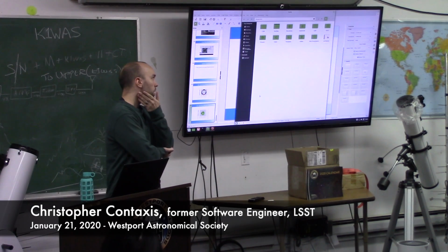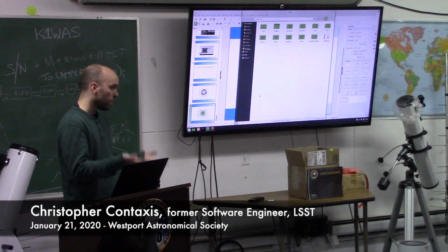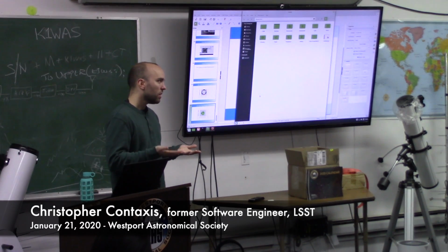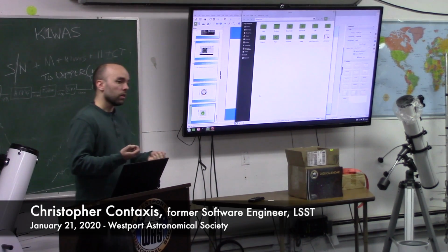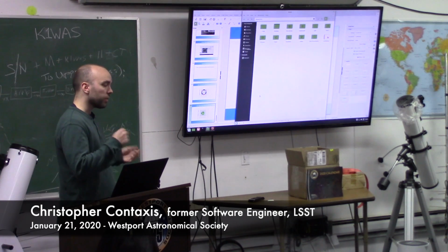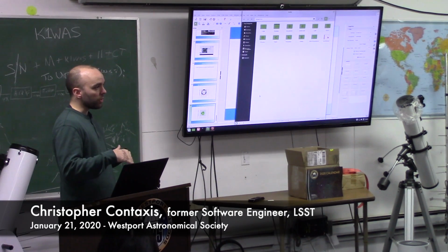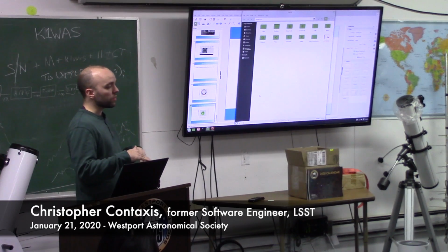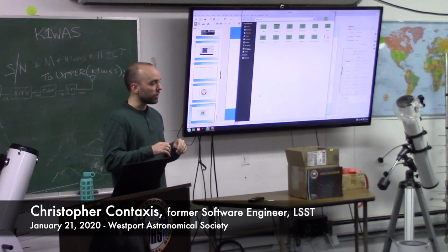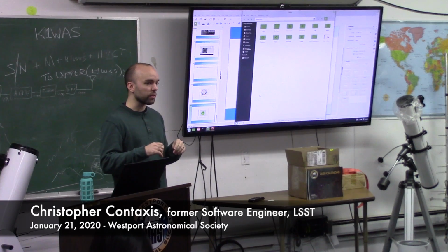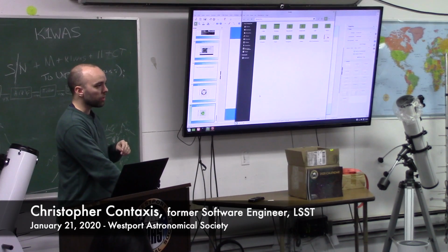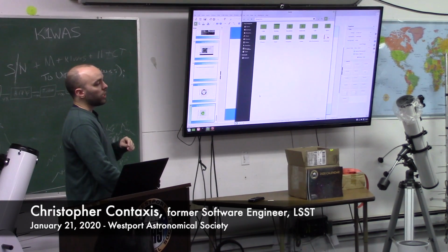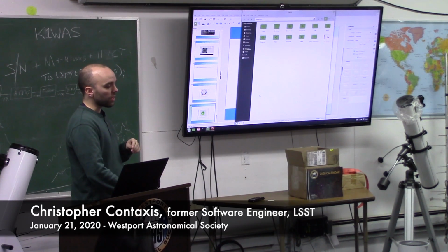So with this, we have to raise it up, and it's about 7 to 8 millimeters that we raise it off of the static supports. And we use the interferometer to see how accurately we got to the same position. And we got there within a half a wave, so roughly 240 nanometers. So we positioned accurately to 240 nanometers a 17-ton mirror. And we reference everything to the primary tertiary mirror because that is not accurate enough.